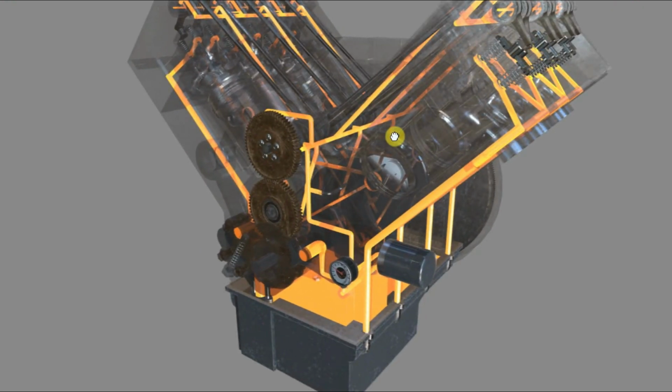Smaller two-stroke engines do not have a separate lubrication oil system, simply because there are too many parts involved and it increases the weight of the engine by quite a lot. So rather than having a separate lubrication oil system, what you'll actually see is that the lubrication oil is mixed in with the fuel itself. If you have ever owned and operated a small two-stroke engine lawnmower or a leaf blower or anything like that, you'll know that sometimes they tell you to add 1 part lubrication oil to 100 parts of fuel oil, or 1 part lubrication oil to 50 parts fuel oil. It really depends on the age of the engine. So you're mixing the lubrication oil in with the fuel.